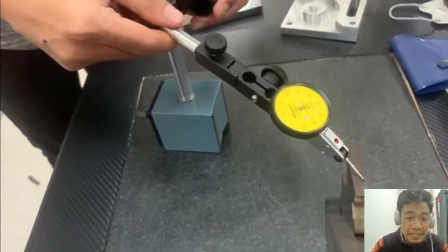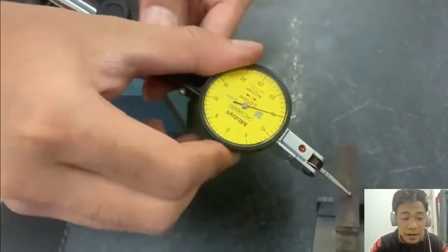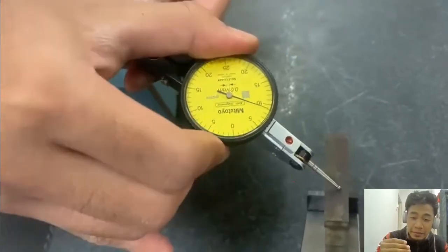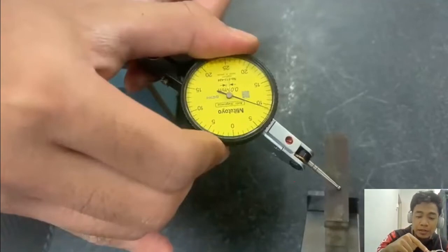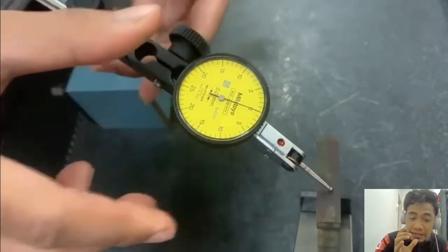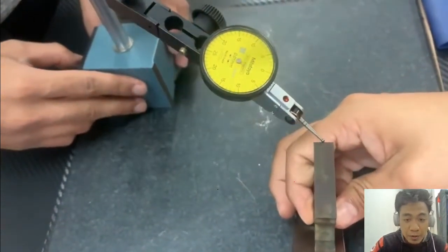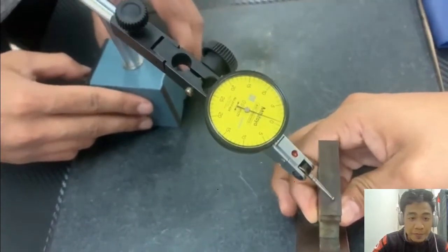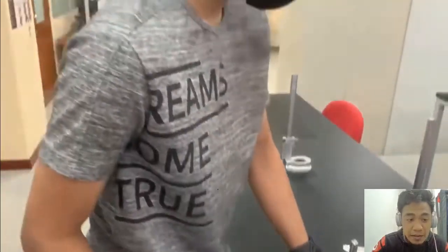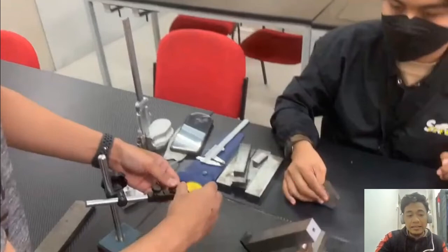This is how we measure. We are measuring using the dial gauge. We take the dial gauge and push it in a little. We don't put it only above, but push it in a little. After that, we set the gauge to 0. Then we need to move it front and back. You can see our part is moving, so we need to hold it. We are checking front and back, front and back. From the video, we see that the movement of the meter is not very far. That means it is in a good tolerance, which means it is 75.